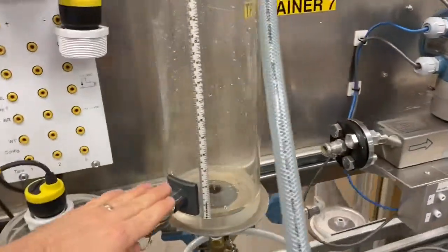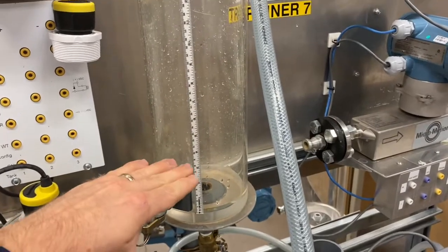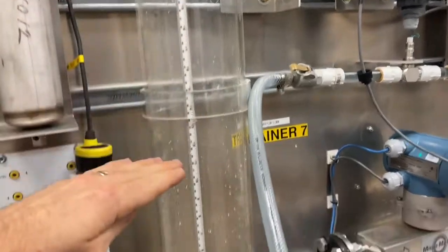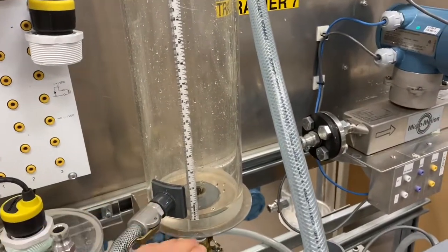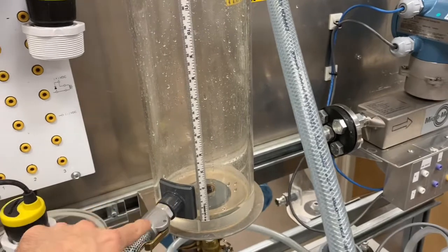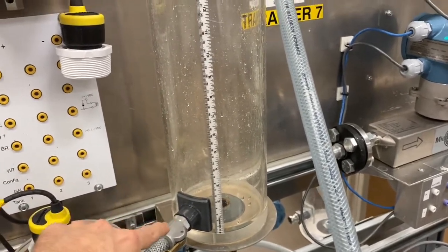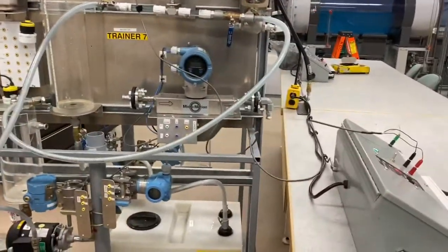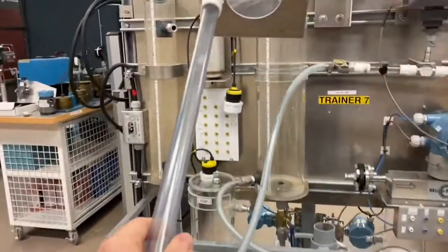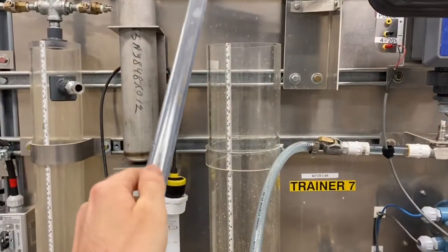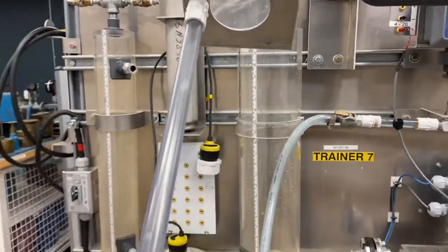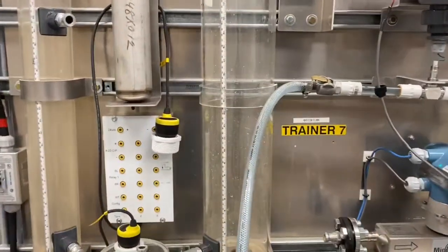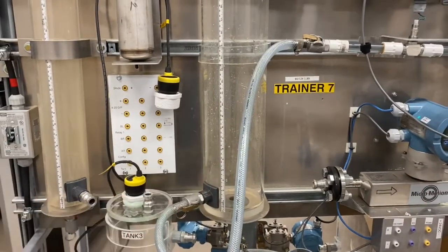We want the liquid to be above our connection point here, so that we're always starting above and finishing up here, so we know the actual volume. Because if we start below here, there's going to be some volume that gets missed in our calculation. Just like we had to modify this tank, we did have a pipe that was installed in the tank as well, and this takes up volume, so that would give us an error as well. So I removed that from the tank.